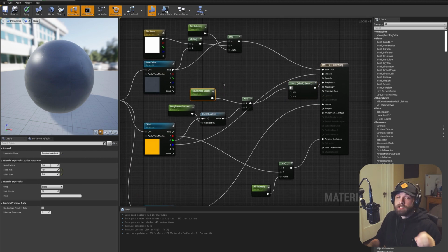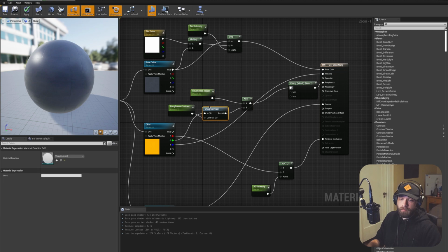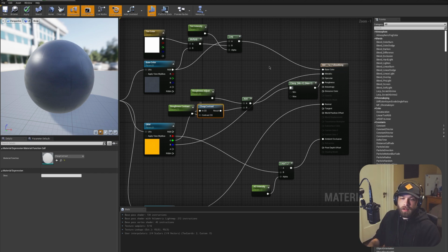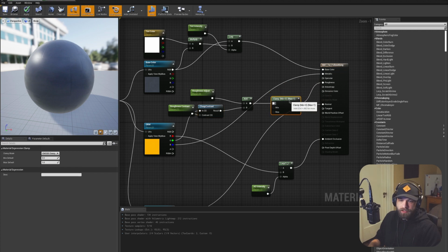Now, to do something a little bit more complicated, and also what creates a little bit more versatility for this, is imagining you can use this master material for instances where you have a roughness texture, or you just want to set a default uniform roughness value for the entirety of the material. What we're going to go ahead and do is create a switch that will switch between using a texture and using a value.